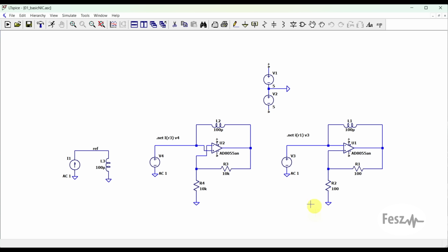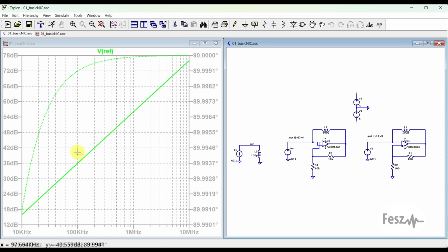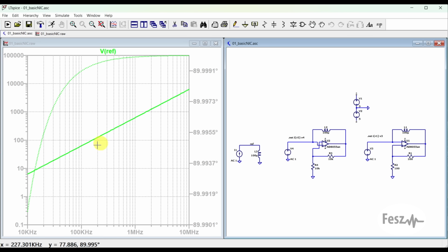So we can quickly confirm that this works by performing a small signal AC analysis. So I took as reference a 100 microhenry inductor, and we will be comparing this to the negative versions built with both the voltage and current inverting configurations. So if we run the circuit and we plot out the voltage in our first circuit, this is proportional to the inductor's impedance, an ever-rising quantity with a plus 90 degrees of phase shift.